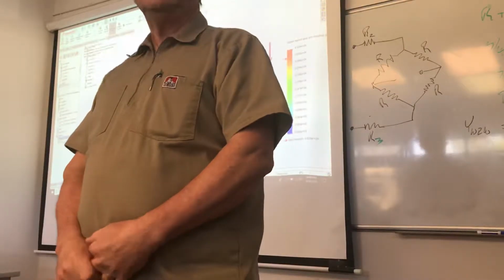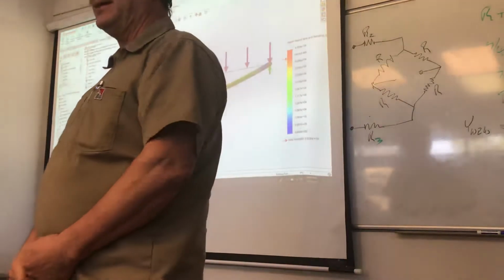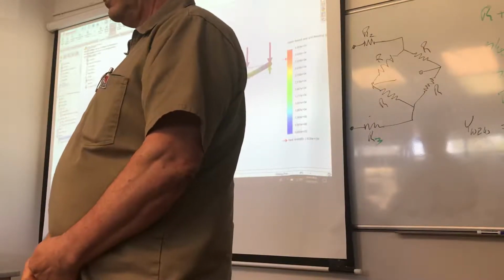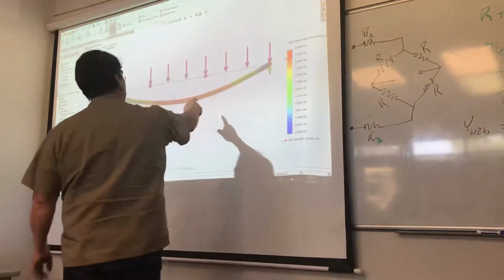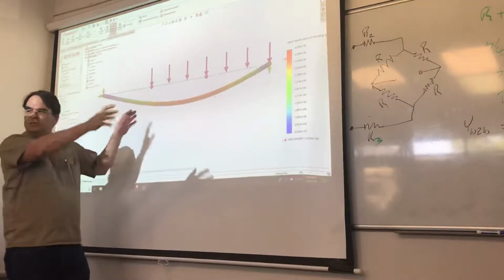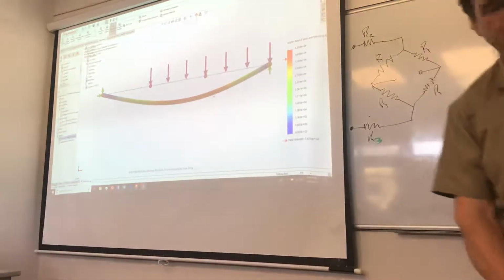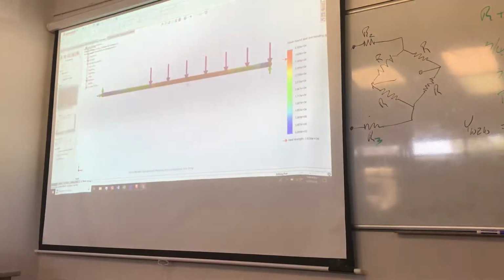So yeah, I'm kind of worried about this. Certainly gonna check it out, but this looks to me like it's going down. And the stress is not a stress concentration. Stress is uniformly distributed over a whole bunch of things. It's not looking good. We can of course do our probe tool and figure out where it's bad. It's gonna be bad right about here. In fact, I picked it first time. Even got coordinates from it there.